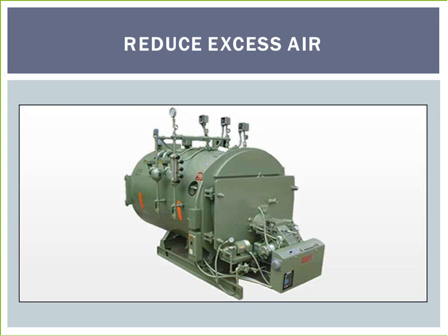Properly operated boilers require a certain amount, usually 10 to 20%, of excess air to ensure complete combustion. However, operating with too much excess air reduces boiler efficiency by heating up and throwing away this cushion of excess air. On the other hand, operating the boiler with no excess air can lead to sooting on the fireside, air pollution, poor efficiency, and even potentially explosive flue gases, so boiler operators tend to have a cushion of excess air rather than a deficiency.